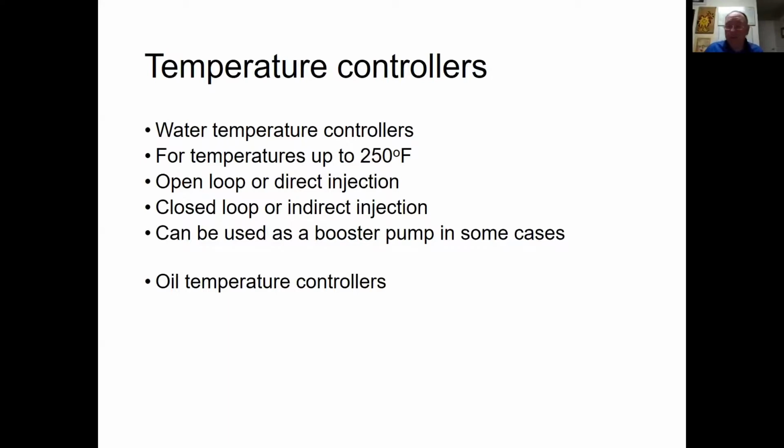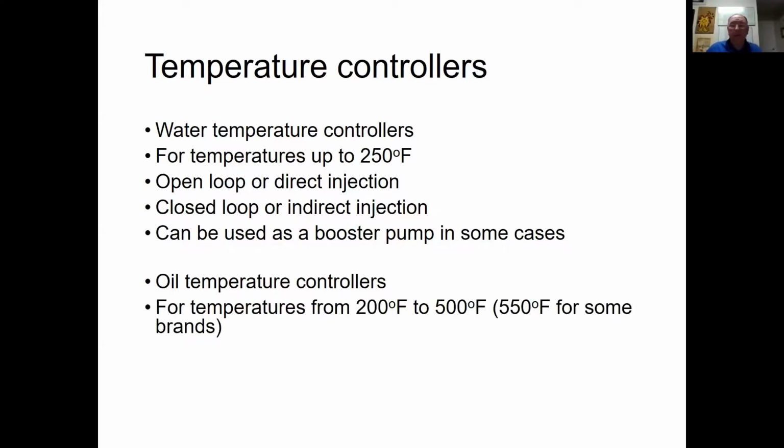They're a little bit different than water temperature controllers. They have to be self-contained, if you will. So where they're not direct injection, they're typically closed loop, if you want to call that, because for cooling they have to incorporate a heat exchanger, and we have to have the cooling source in order to extract that heat or transfer it.